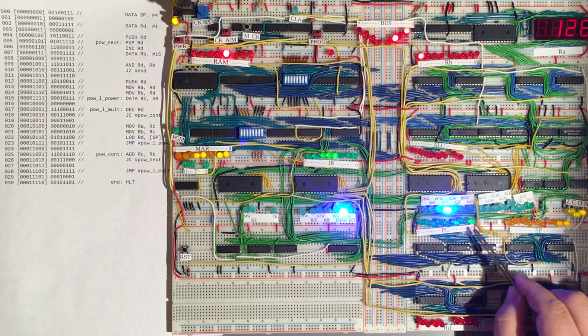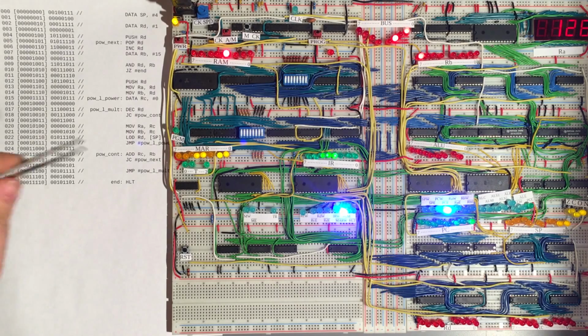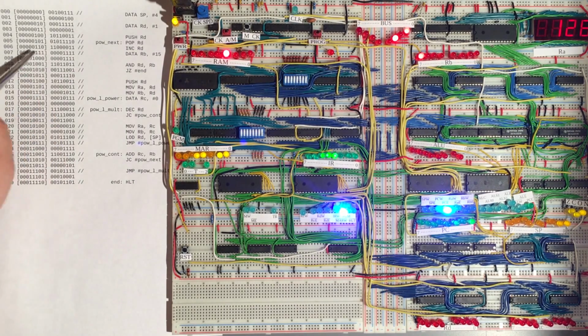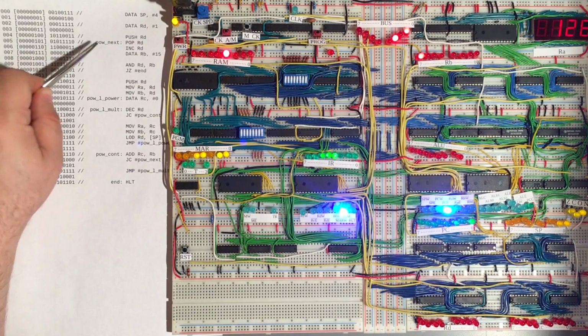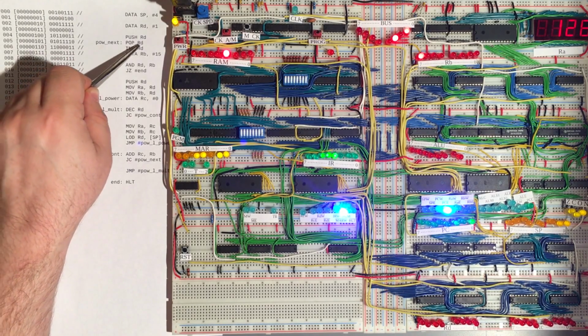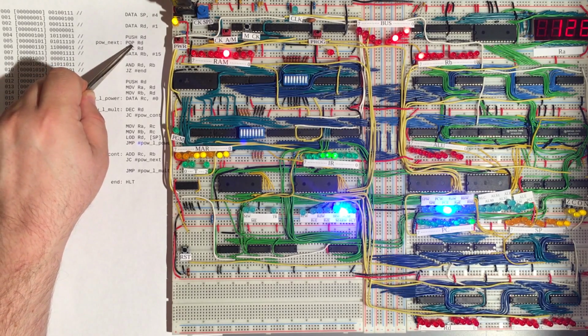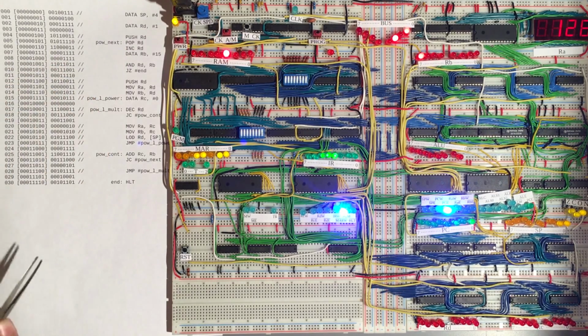This is where our CPU is located at the moment. Our program counter contains a value of 5. We're at time t0, and so we'll start executing the instruction at address 5 here. That turns out to be a pop instruction, so we'll have a look at what sort of microcode we might need to execute that pop instruction.